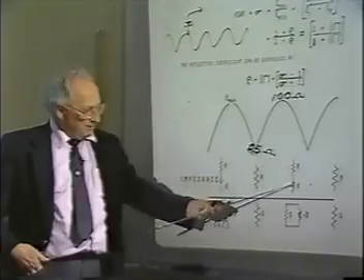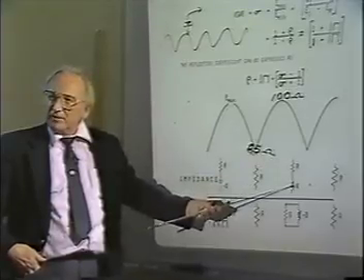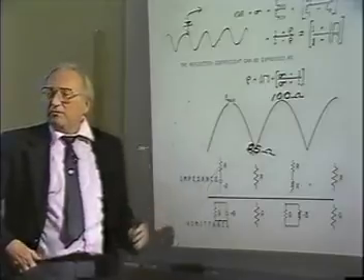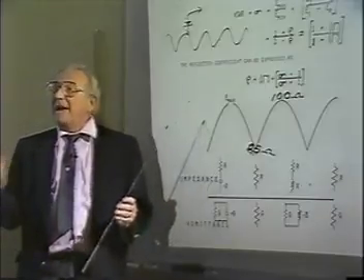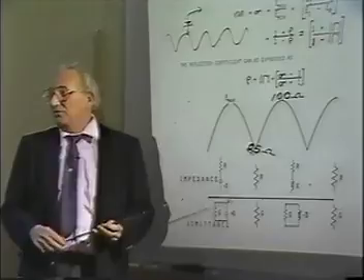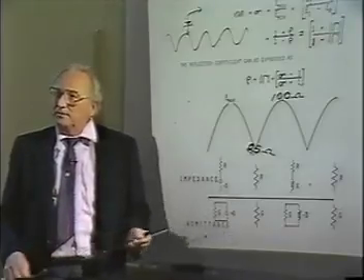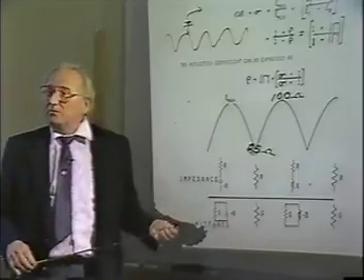If you were over here, you'd put a capacitance in to get rid of the inductance. What would you have left? 50? Over here you'd have left 50. You have what you call a matched transmission line, because the only thing you have left is 50. If it's a 50 ohm line, then it's matched, isn't it? So that's the whole theory of matching.